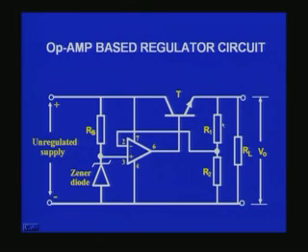That means it is regulating the output voltage by using the pass transistor T, the transistor that you have here, along with an error amplifier and a Zener regulator. This is a slightly more involved circuit, but it is very useful for regulating an unregulated power supply. Nowadays standard regulated power supplies can be obtained very quickly by using what are known as three terminal IC regulators.